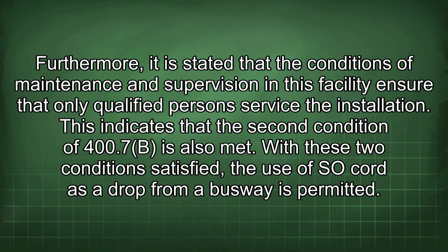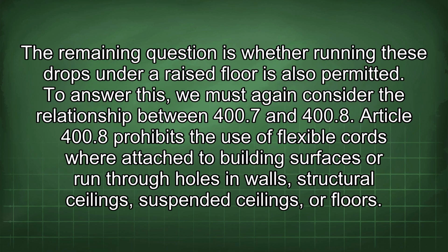Furthermore, it is stated that the conditions of maintenance and supervision in this facility ensure that only qualified persons service the installation. This indicates that the second condition of 400.7(B) is also met. With these two conditions satisfied, the use of SO cord as a drop from a busway is permitted. The remaining question is whether running these drops under a raised floor is also permitted. To answer this, we must again consider the relationship between 400.7 and 400.8.